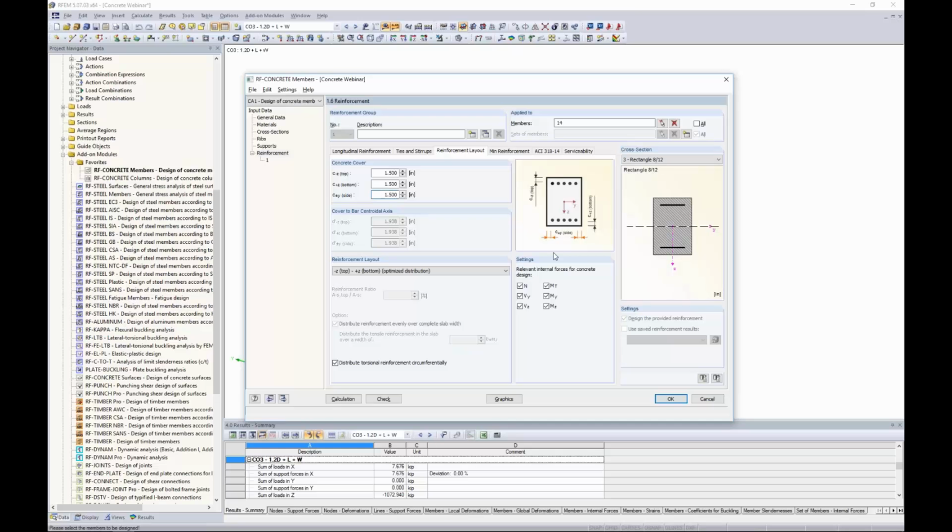This is clear cover. This is the distance from the edge of the concrete to the edge of the reinforcement. Shear ties are considered in this as well. So this is why the cover to the centroidal axis is grayed out, because as I adjust this to maybe 2 inches, the cover to the centroidal axis will be adjusted as well based on what we put in there for possible bar size.